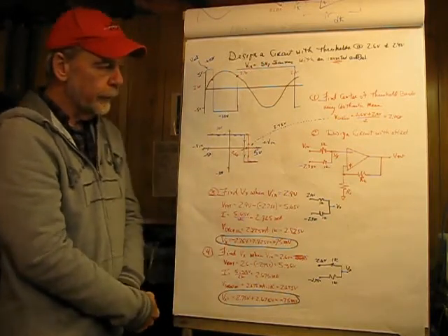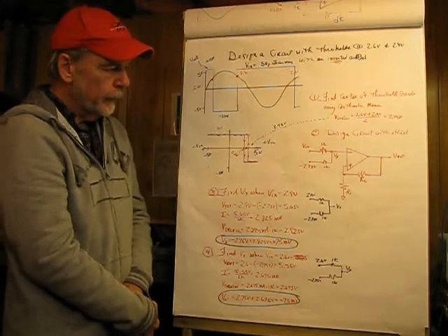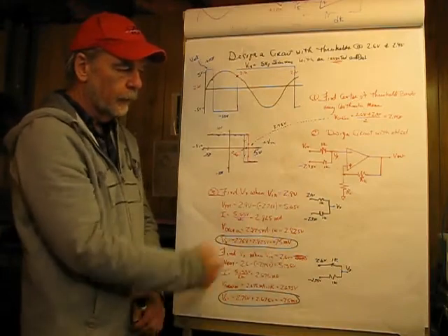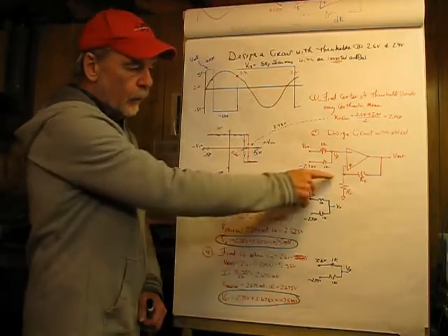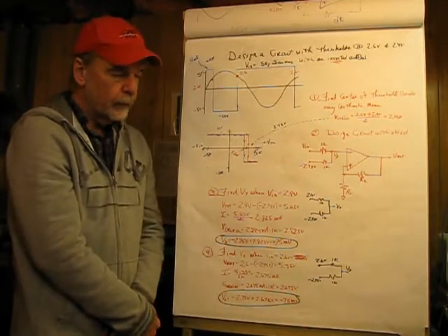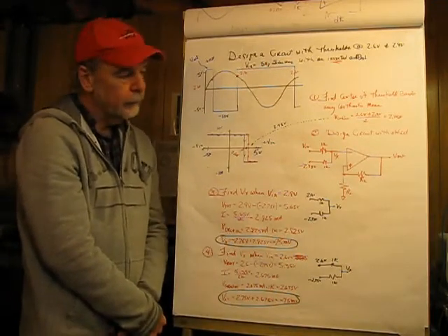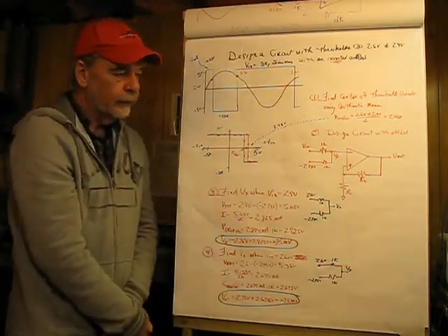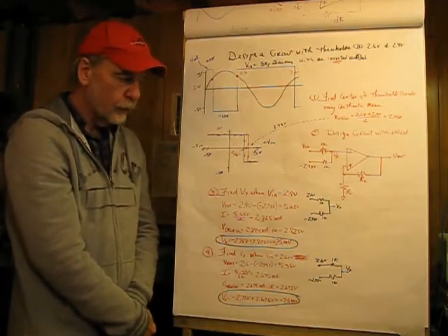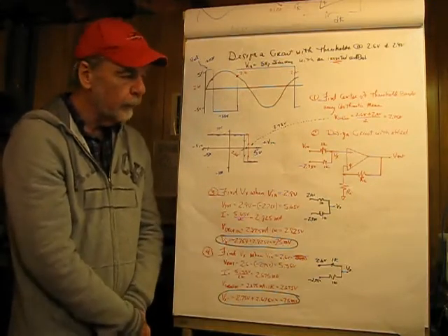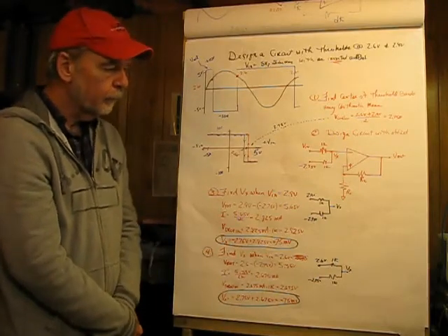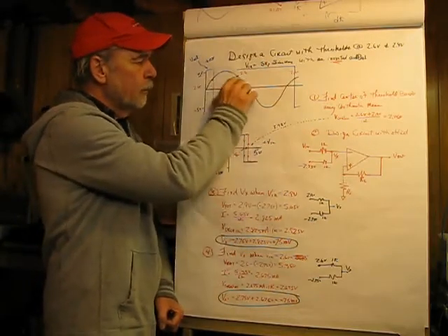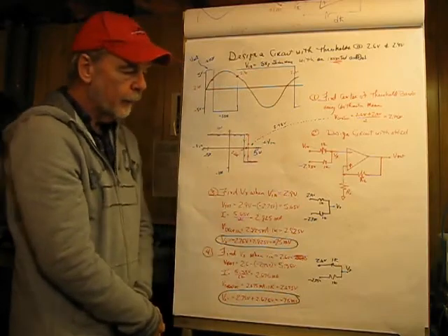So once we know the center here, we can design a circuit. What I'm going to do is set up an offset, which is going to take our input voltage and translate that down and allow us to do comparisons relative to 0. Now, this is the second approach for me. What I tried before was feeding something into this input, and what I found with that design is it failed because there was no solution to the equations. Oh well, time to back up and figure something new out. So if I make this 2.75 volts, I can reference right to the middle of this point, and I'm thinking that should work.